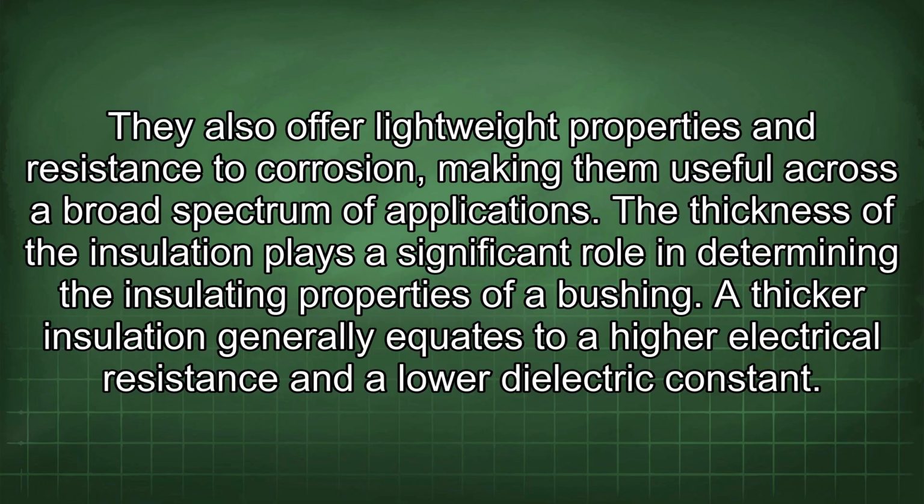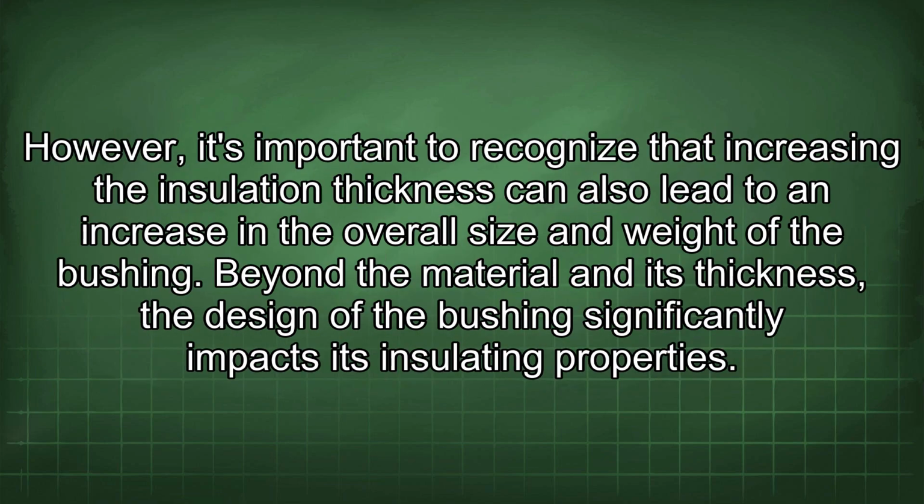The thickness of the insulation plays a significant role in determining the insulating properties of a bushing. A thicker insulation generally equates to a higher electrical resistance and a lower dielectric constant. However, it's important to recognize that increasing the insulation thickness can also lead to an increase in the overall size and weight of the bushing.